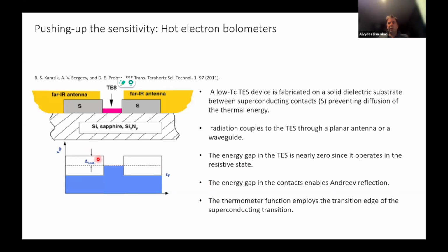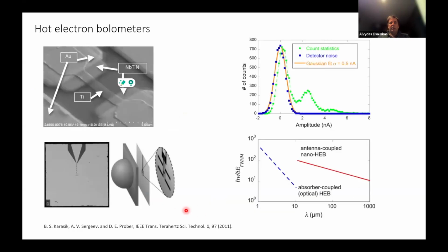And that could be used as an electrical thermometer, looking for the change of temperature here, or exploiting the sharp TCR, temperature coefficient of resistance. Once we employ that, also the very same way, using a silicon lens or substrate lens coupling into that antenna device, and this antenna is actually, you see, a complicated antenna, not the most simple one.